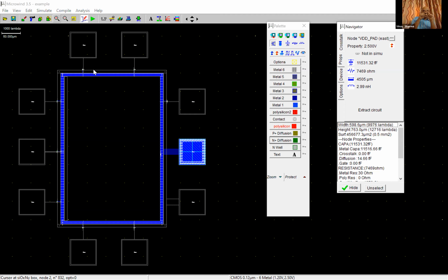You will place your circuit in the center of this ring. So anywhere you require a VDD, you just connect a metal line to this IO ring. That's it. And this would be the VDD line. So anywhere you need a power supply, you just go and connect it. It is just like running a power supply across the circular path of the entire IO chip, and wherever you require VDD, just connect to it.